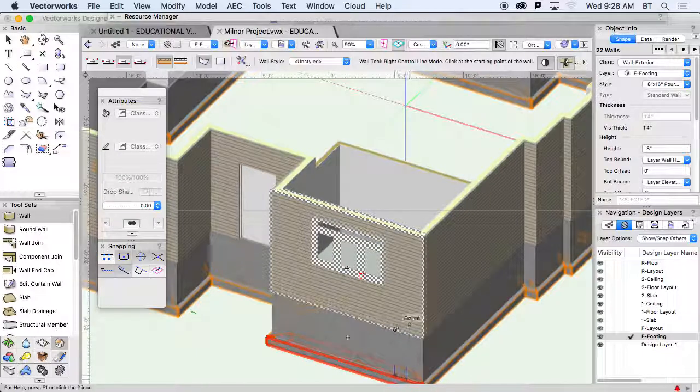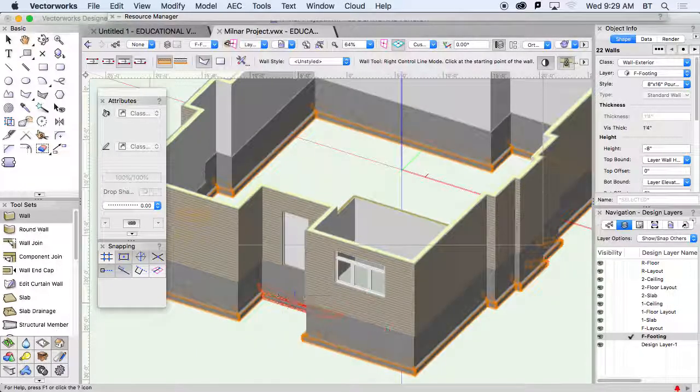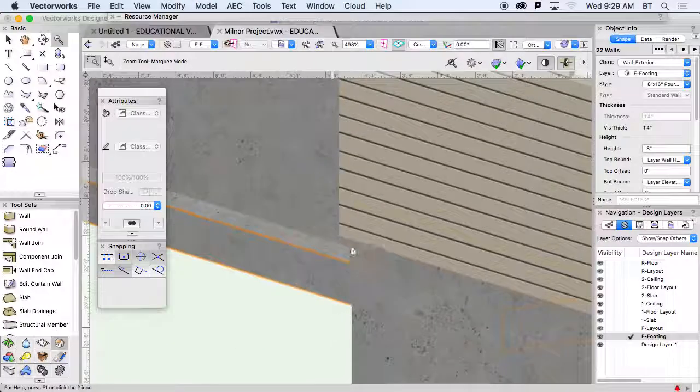So we want to have all this, and you can even see that my siding is going to overhang a little bit, right? Because that sheathing is lined up with the concrete. So then you have your rain screen and your siding, and you want